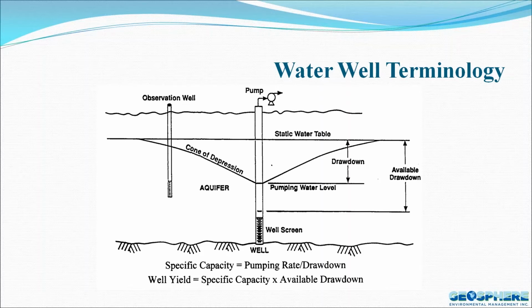Remember back from our introductory hydro courses or basic geology courses that the static water level is a dynamic feature. It does not stay in one spot throughout the year. It moves up and down depending upon the amount of recharge we get in the springtime, and as we go through the growing season, the water table begins to drop naturally because of seasonal demands by vegetation or by everyone. So locally around here, to see a 3 to 10 foot drop in the static water level over the growing season, over the summer, is not unusual. So we do see that.